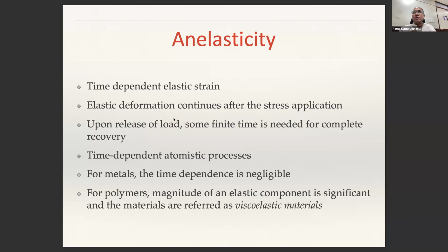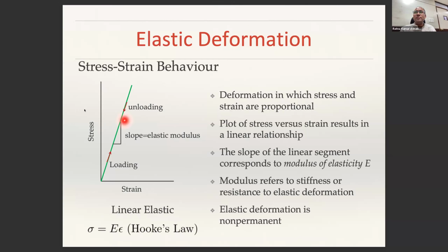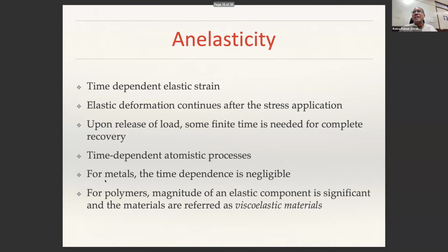here, in pure elastic deformation, if I remove the load, as soon as I remove the load, the strain becomes zero instantaneously. There is no time lag. That is what a pure elastic deformation is. Whereas if we are dealing with an inelastic deformation, upon release of the load, you actually require some time for a complete recovery. Right? So this is what we call a time-dependent atomistic process.